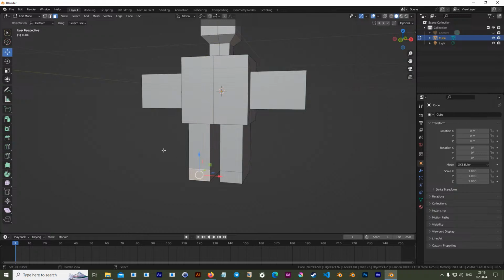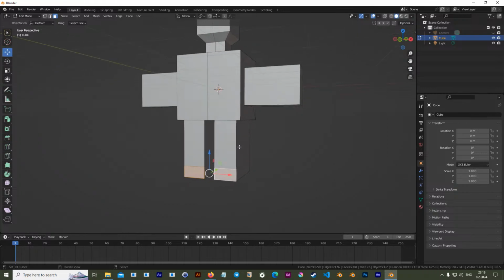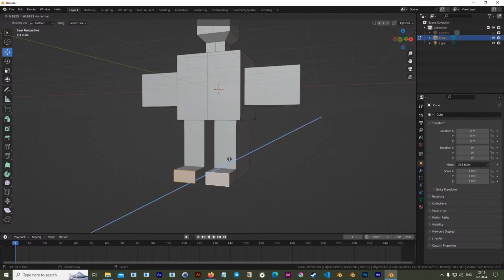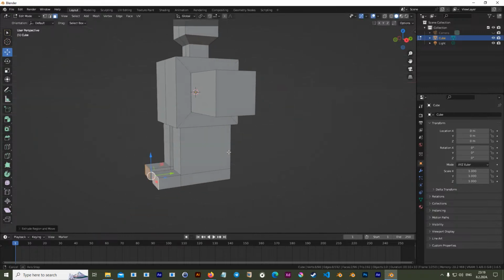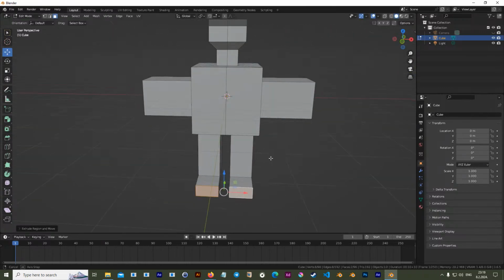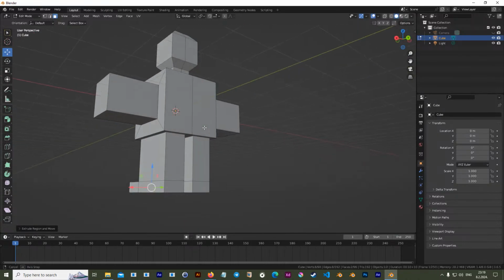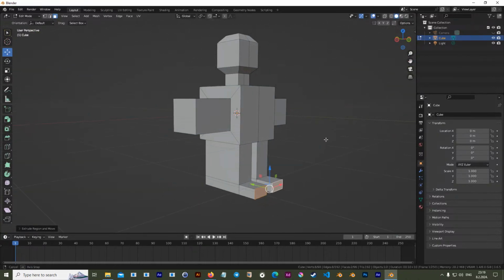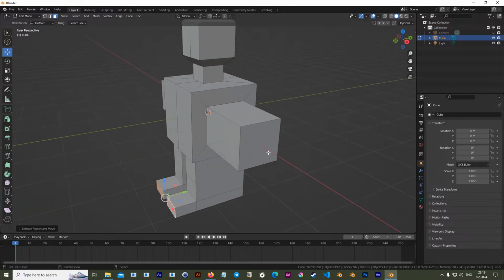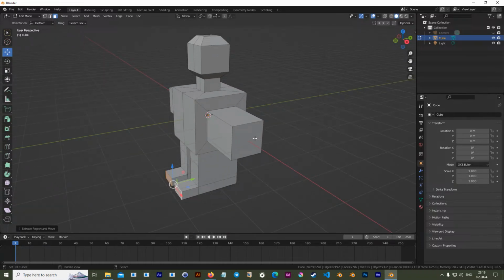make legs. Press E once more, extrude just enough so you have your feet. Select the front faces of your feet, press E, extrude upwards. Now you have some kind of feet. This looks funny. It's just some giant bulky figure. But we created it. If you followed me, we created it almost all on a keyboard.